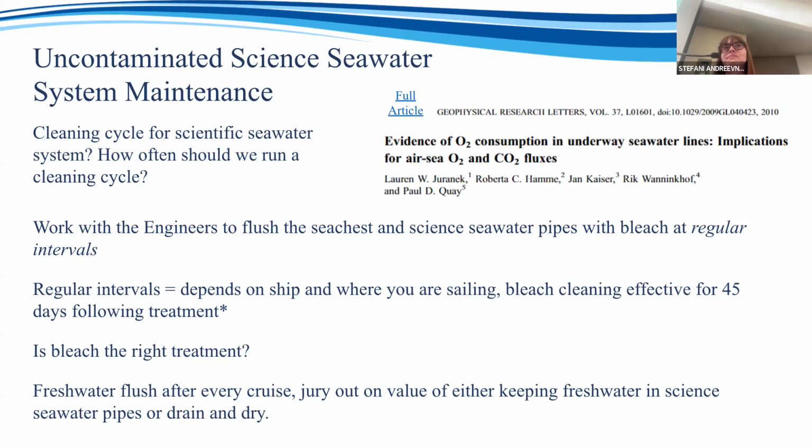But I also have an opinion on diaphragm pumps. We have seen nothing but problems since they have been installed. Flow issues, flow rate issues, the pulsating effect they have, shredding apart the diaphragm to try to stop the pulsating, them being so loud that people can't sleep, even though they're in the bow thruster space. But the impeller was also bad. My predecessor probably burnt out 2 or 3 of those, and they were also expensive.